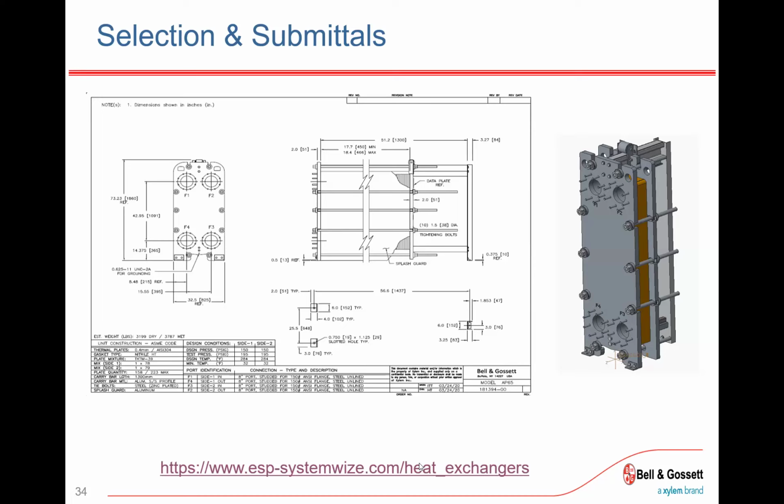All right, moving on. If you had a heat exchanger in the field and said, I wonder what I can do with that heat exchanger, in terms of performance you can put performance in, then select rating. Then I could say, okay, I have the heat exchanger details, which we could pull from the serial number. We could build it and say, you can achieve those new conditions with that old heat exchanger, or maybe you add X amount of plates and we can achieve it. It's just a nice tool to have.